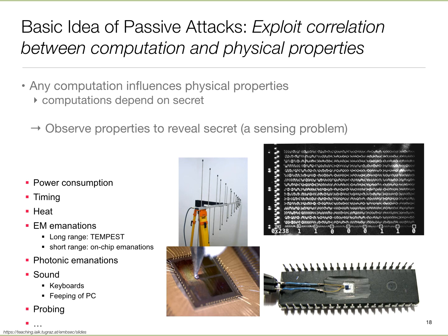Timing, heat emanation, electromagnetic emanation, both long-range variety, like the one which I had cited from that World War II example, where it was up to 80 feet, and then there are also very short-range emanations. Even these integrated circuits emanate electromagnetic things, but they can only be picked up right close to the die. So your probe has to be on top of the chip. But if you have the device with you, you can certainly do that.